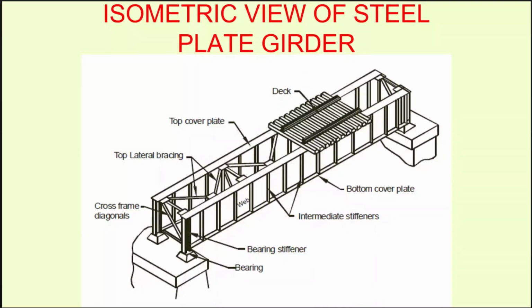Now one point here to understand, whenever we are analyzing bridges or the beams or the girders, we typically assume it as a line element and then we do analysis for the bending moment, shear force, etc. Actually, these structures are three-dimensional, they have finite depth, and because of the finite depth, when they are subjected to bending, the ends of these bridges get rotated, and because of the rotation and the finite depth, there will be a lot of change in the length of the top fiber as well as the bottom fiber that needs to be taken care of at the time of further analysis, and it needs to be seen that there is adequate space available for the bottom fiber or the top fiber to deform, so that the bridge is able to function properly, otherwise it will generate secondary stresses.